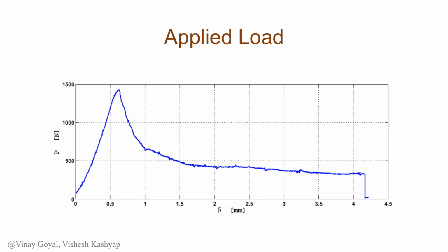From the graph that we've been given, we can make out that around 1400 newtons is our failure load for the adhesive. And so 1400 newtons is the load that we're going to apply on our double cantilever beam for this video. Let's go to ABAQUS now.